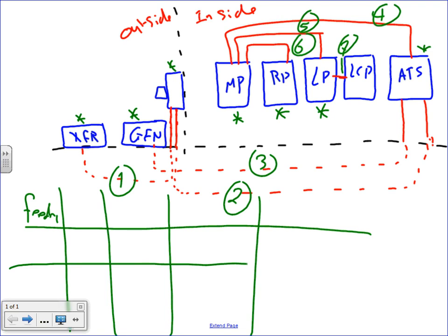We always did, we said feeder. I'm going to do one of them. So this will be feeder number 1. Conduit. Let's just say the conduit that we were pulling, we sized, right? We came up with 500. Let's call it number 1, and let's say 5-inch PVC schedule 80.